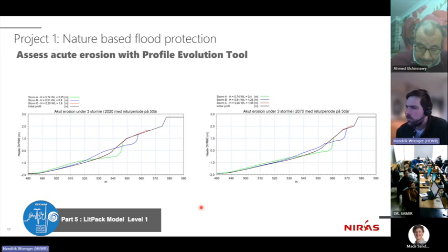errors. For some of those errors, we try to quantify them by sensitivity studies, right? You sometimes just run your model with slightly modified parameters. For example, you can say, okay, what if my significant wave height is 10% higher? I run it again, and then you get a quantification of that potential error, right? You can do these exercises, but still, you will probably want to establish a monitoring program after this beach has been established, and then long-term compare your